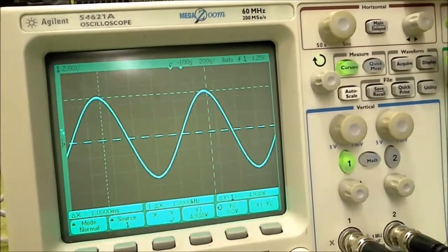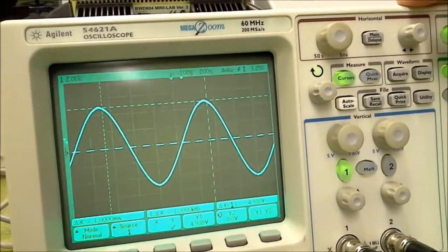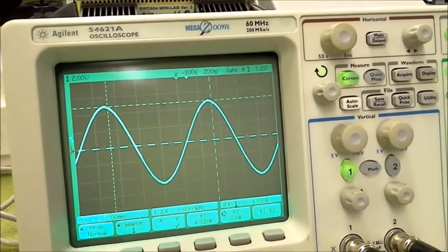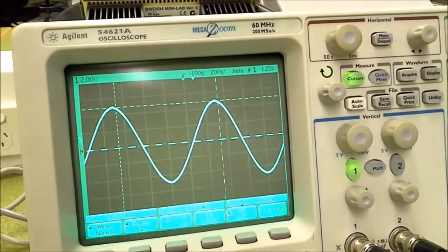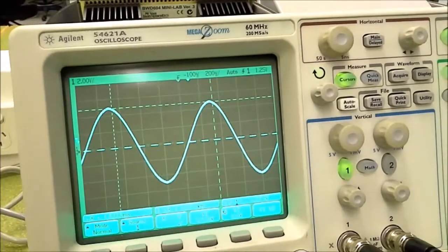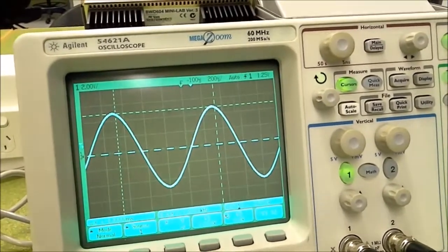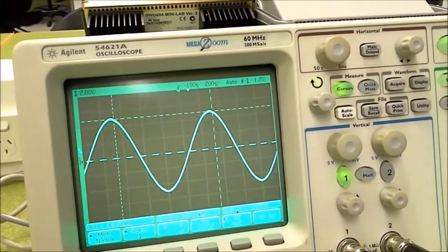So the peak amplitude is, as you can see, delta y equals minus 4.93 volts. It is minus because y2 is at ground level. If we put y2 at the positive peak and y1 at the ground, then you will see the amplitude is positive.